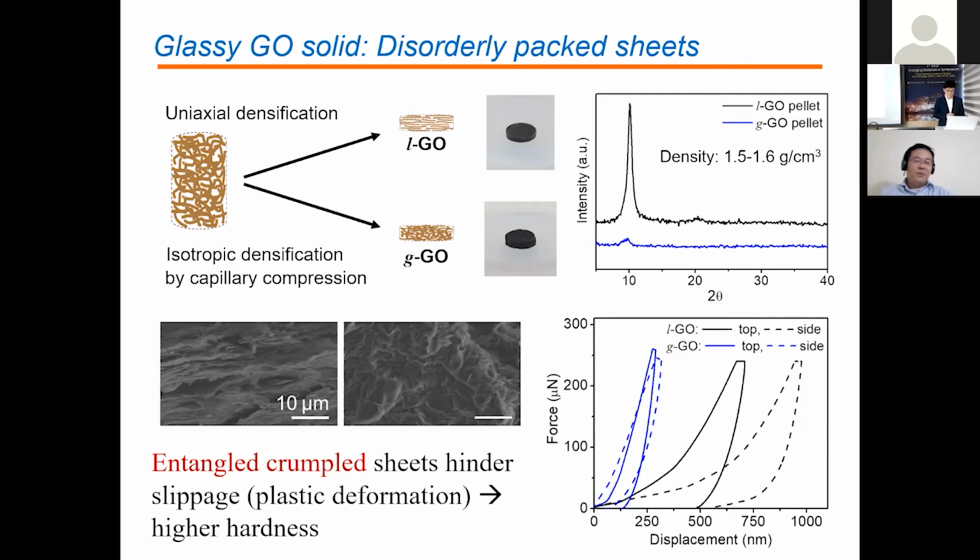Now after manipulation, for the graphene oxide one, if you, for example, roll it to force the lamellar arrangement, then it gets harder because it will no longer be as moldable in the ribbon state. To return it to the moldable ribbon state, you will have to knit it. You have to fold the ribbon up and knit it. We use a mechanical shaker to help to knit it. Knitting helps to randomize, or again, to increase the disorder in sheet stacking. So that would be one way to do it.